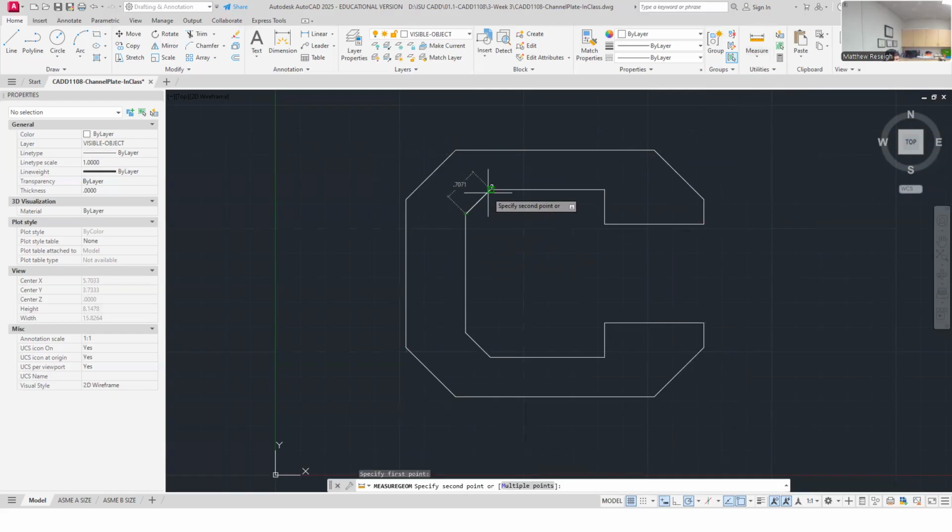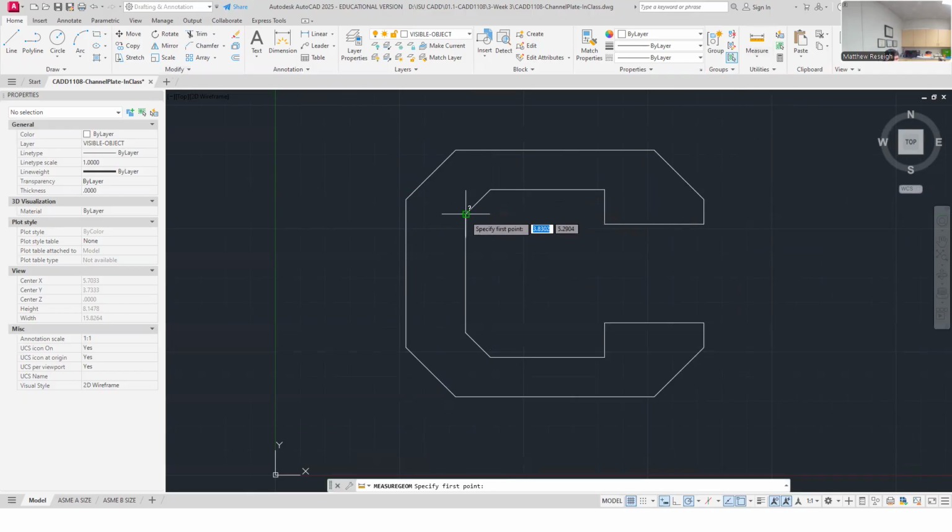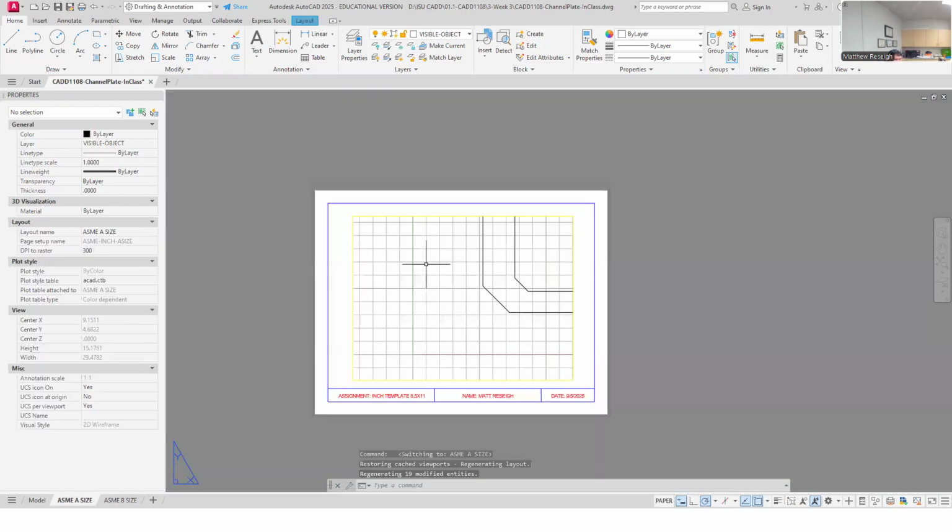Distance here, I'll click there and kind of hover here and pull it over. Yeah, that's 1/2 inch, and then I'll hover there and pull it over. Yeah, that's how you get those green tracking lines to show up, is kind of pick a point that you want to try to think about tracking. And sometimes it takes me a couple times to get it tracked into the right spot. Like I'm clicking on that one and then I'm hovering here. I don't click there, I actually hover here. Just kind of hover, track down. Yeah, it's a 1/2 inch. So I've done myself a favor and double checked that before I've left to go into paper space.